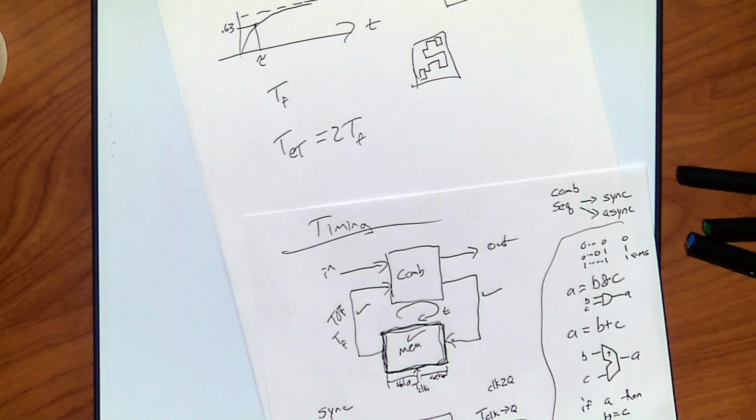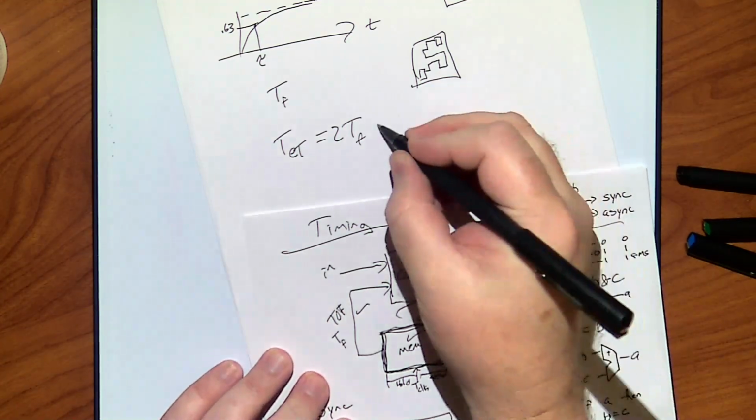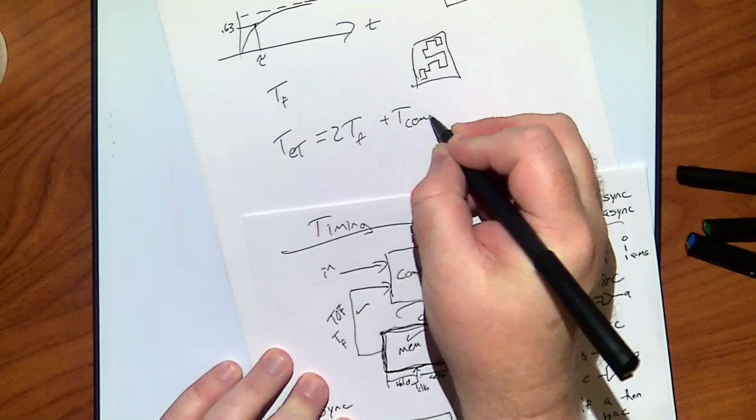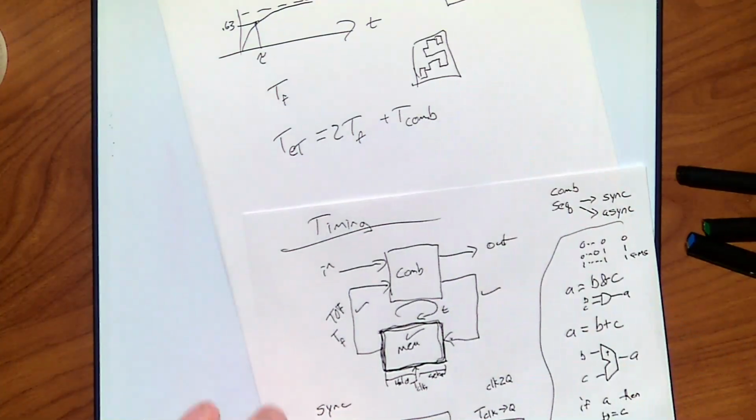The key thing for us is I know about how long each gate takes, so I can tell in the logic family what a gate is. I find out how many gates to make it through. Now I can get what the time is of the combinational logic, which we call T comb. It's based on how I build a particular item and what the logic family for that is. Right?